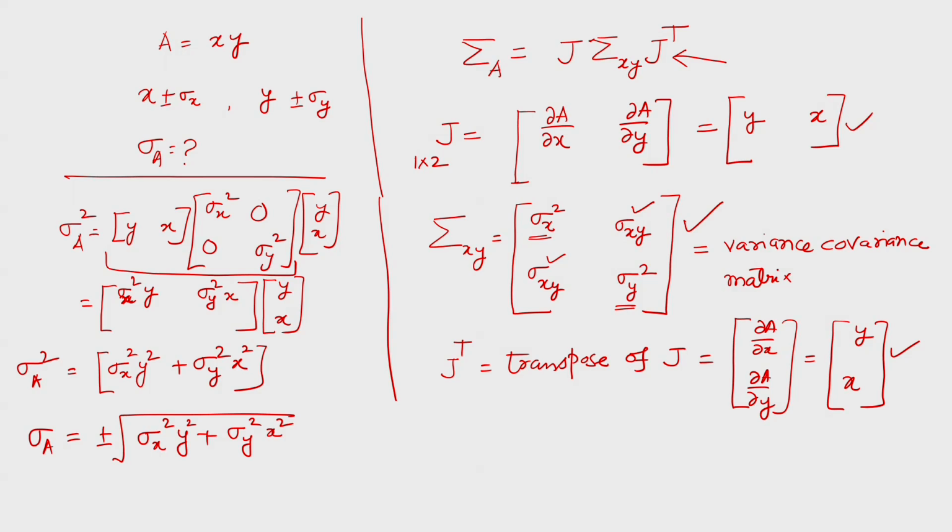measure the length in general one time or two times, but I know from experience what the value of sigma x is. So, I assume sigma x and I assume sigma y. Generally, we assume based on the least count of the instrument, that is the tape, or if I am using a total station, then I will use the least count or accuracy of the total station. So, generally we assume sigma x and sigma y and we do not measure them.